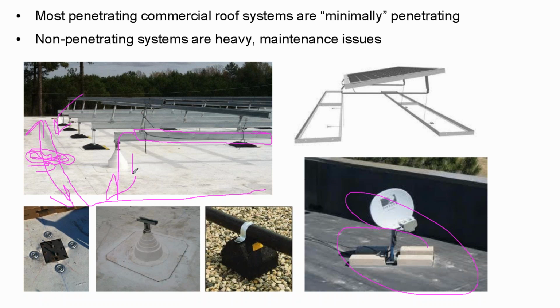By the time you get to the combiner box, where all this conduit would come in together, that conduit would start pulling out of the box, and then you get a conduit busted off, and now all of a sudden one of those cables can start fraying and ground faulting, and under the right circumstance, it wouldn't be detected by the commercial inverter ground fault protection system because of this blind spot issue, which has since been